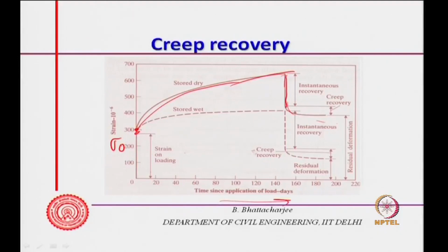So, this is actually instantaneous recovery, some of the elastic strain will be recovered, but it does not come back to the original state, it stops here only. With time some amount of recovery occurs, this is called creep recovery. My residual deformation is here. So, there is creep recovery, and there is residual deformation still remaining, which does not come back to 0.